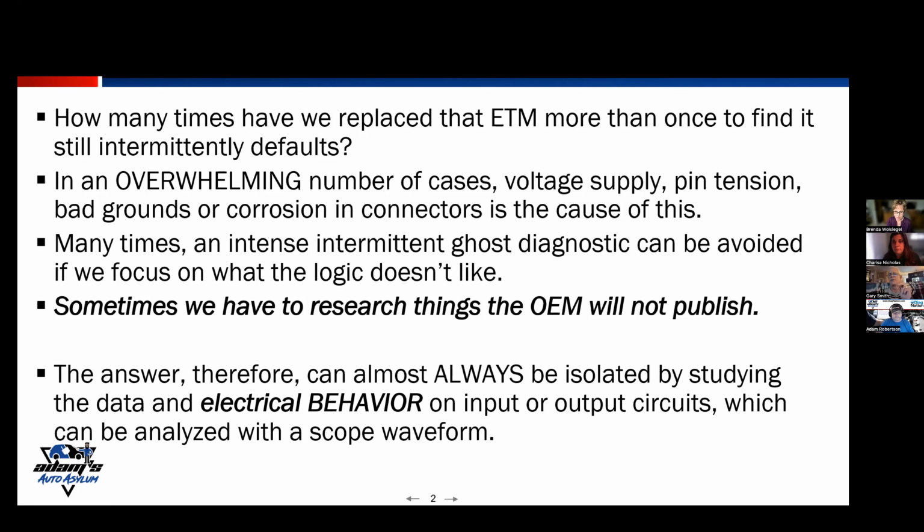So this is where we get into thinking outside of the box a little bit in our diagnostics to see if we can actually track this down and get an answer. A lot of times, many of the ghost issues that we're experiencing, especially where you get a Valvetronic fault, a VANOS fault, a throttle motor fault, something that actually makes the vehicle default and drop the throttle control away from the car, or something that drastic, we're going to want to point ourselves in very certain directions. I think you're going to see as we go through this.